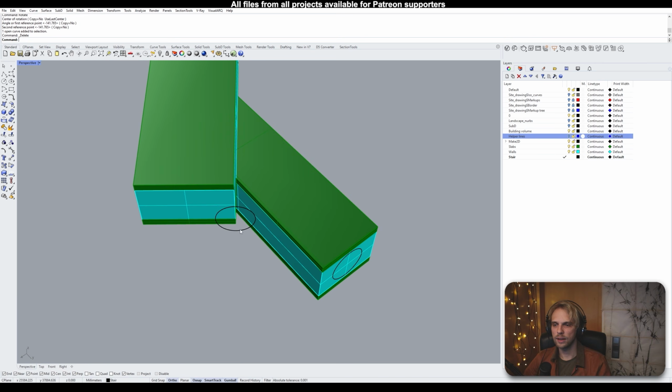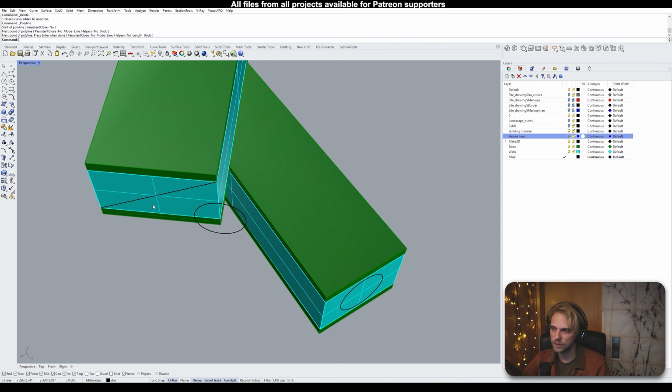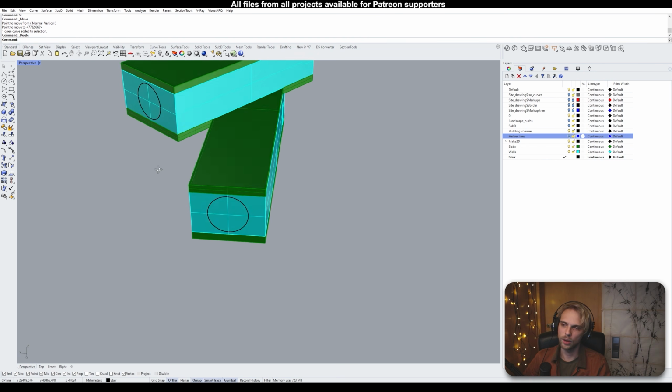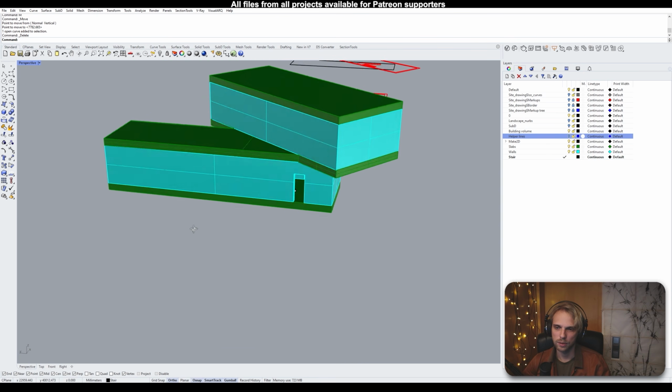After this is done, now it's just the time to position the circle in the middle of this wall. So how do we do that? Well, same way we did the previous one, diagonal, select the circle, move from the corner point here to the diagonal midpoint here, we're done. Okay. That took a while. With rectangular parts it's a little bit easier because you can use three point boxes and so on, but hey, whatever works, right?